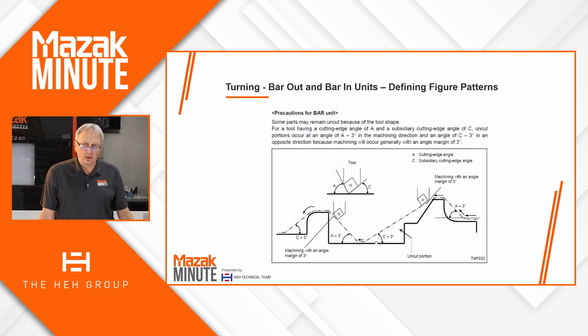Lastly, just as a precaution, when you're doing a bar out in the box, remember that's the ones that start in the middle, or in this case you see how they're cutting from the front and then they're coming down. Well, the Mazak is actually monitoring the front and back edges from the description from the tool data page. So on the front side of the tool, if we look here in the section, I have an A degree, which is my lead angle.